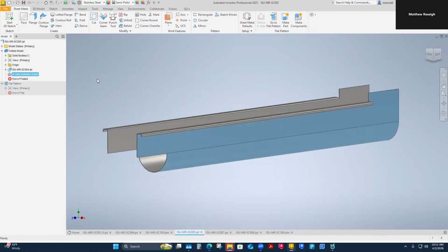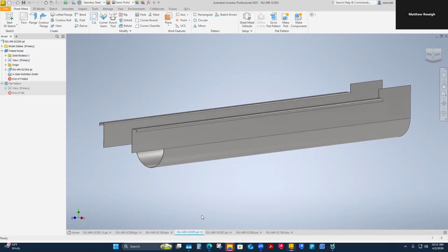Yep, identify a side and then create that flat pattern. Otherwise, you won't have that as a placeable. And I'm generally checking these parts before I ever go to sheets because I know I'm going to make a flat pattern. I'm checking to make sure they unroll. I know I've got one part that still has an issue. It won't fold, it won't unfold for me. So it's part of my process getting ready for sheets.